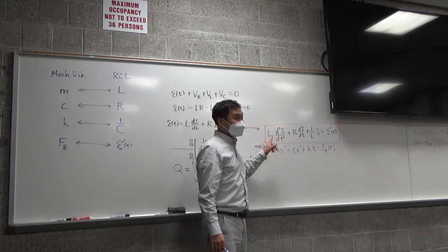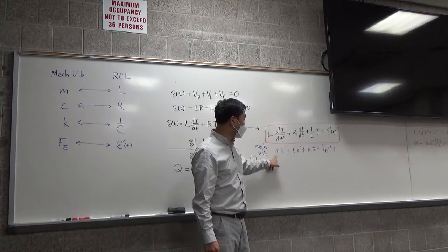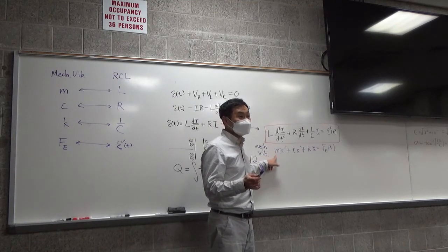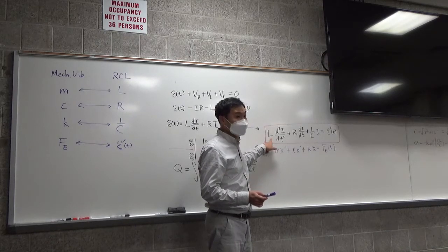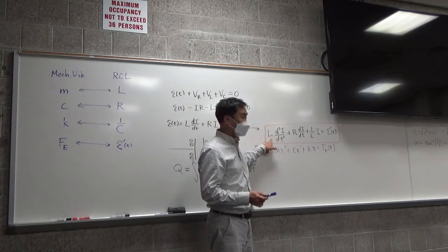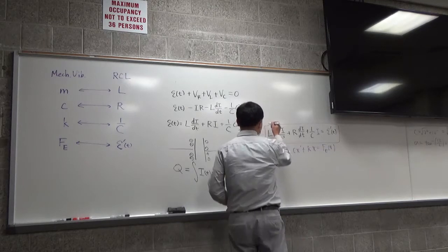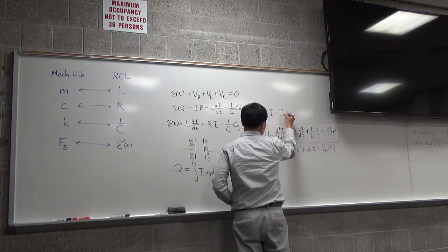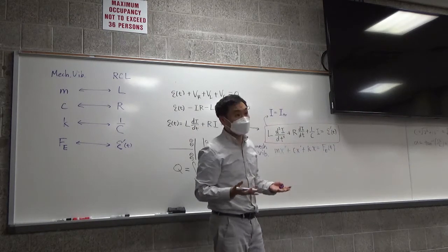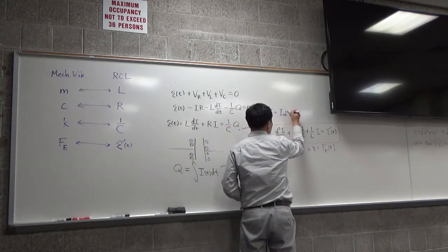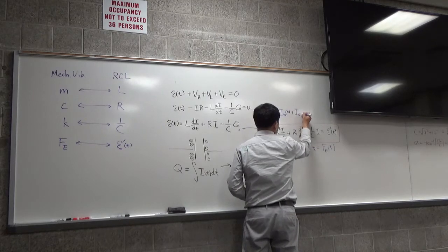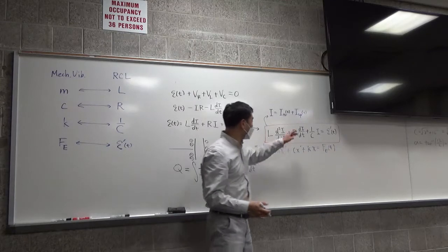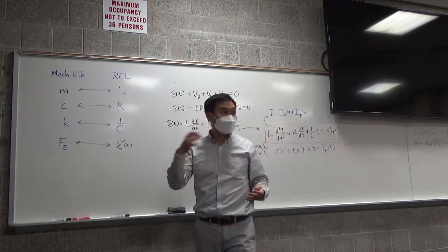Okay. Now, we also learned that for this one, there is the transient solution and the steady periodic solution, right? There's also a transient current and a steady periodic current. So, in other words, this one will have a solution structure that looks like I transient, which decays to 0 very fast, plus I steady periodic, which perseveres, because the input voltage is continually feeding energy.